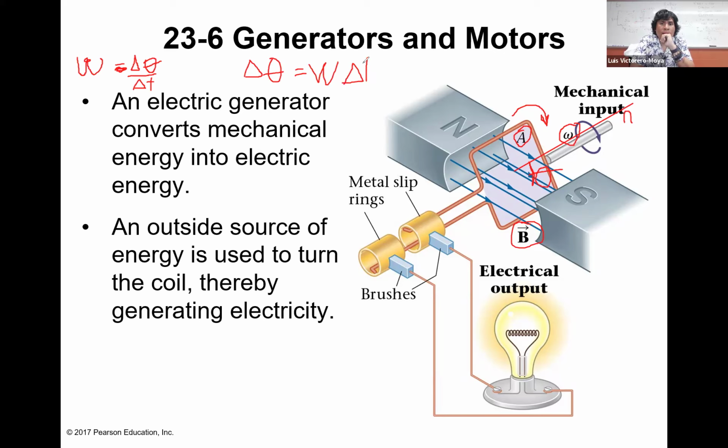So now we're going to apply Faraday's law. Faraday's law is the magnitude, absolute value of negative N, where N is the number of turns. This is one loop. It can be many loops, by the way. So N is still there. The rate of change of flux, right? Flux will be the magnetic field, the area, which are constants, multiplied by the cosine.